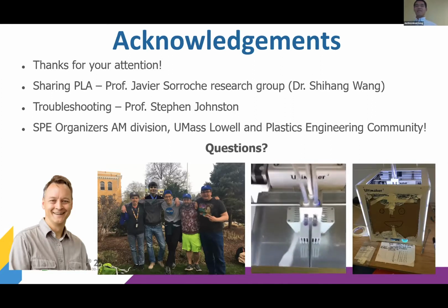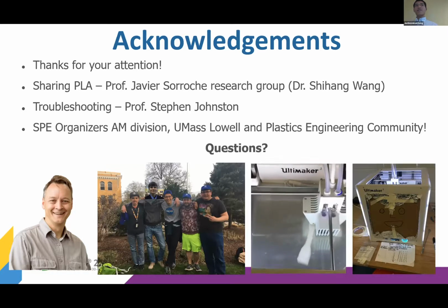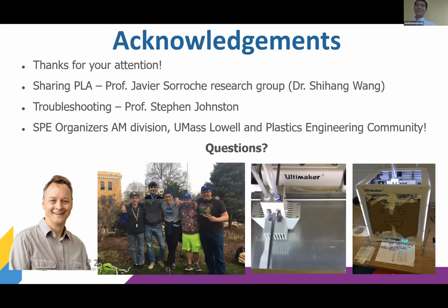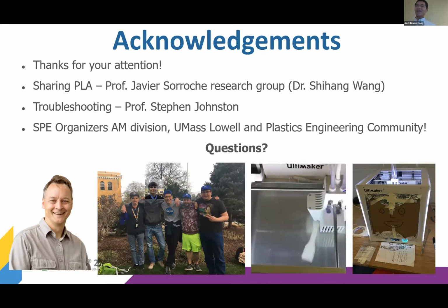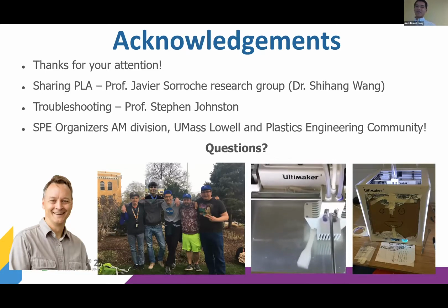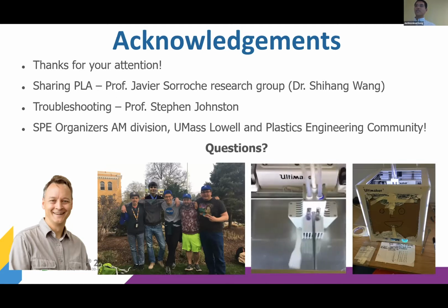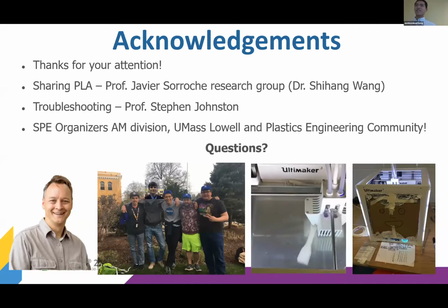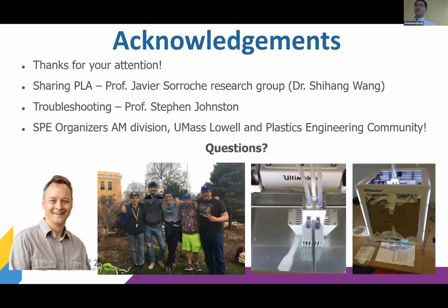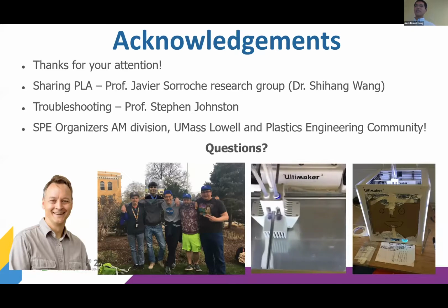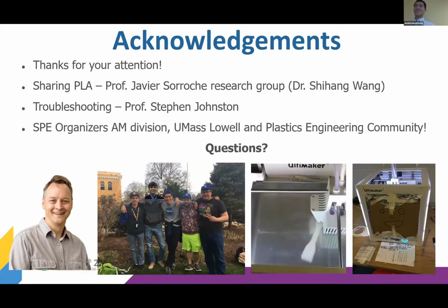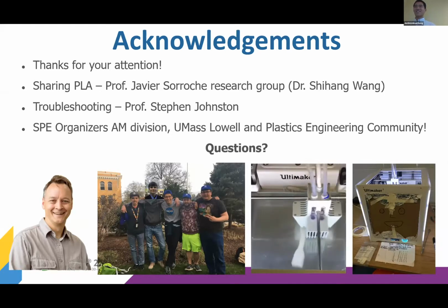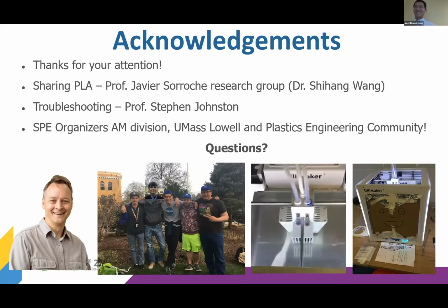In terms of whether we intentionally had a lot of variations, no, we never wanted to create bad filament. However, I think that was also a function of our single screw extruder. I don't think we had a proper screw, or it wasn't as consistent as we wanted. We're also using an older machine, so that affected it a lot. So we did not intentionally make bad filament, but it ended up being bad filament, and we made the best out of it.